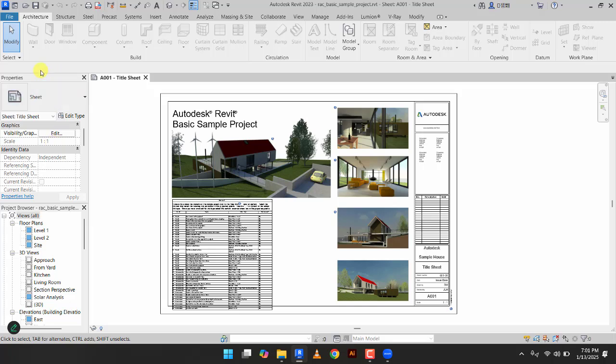because we said Revit is a BIM software, right? So your properties is where you can go and change the dimensions we spoke about. So if you select a wall, you want to change the size of the wall, the height and all that, you have to do it under the properties. So if the properties is not there, you can't determine the wall you use, right? You select a table, chair, you have to see them under properties. That is why the properties is important. It has a lot of other functions which we'll go to later. Primarily, that's what it's used for.